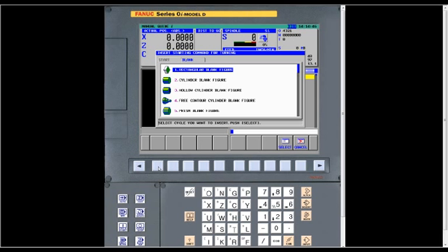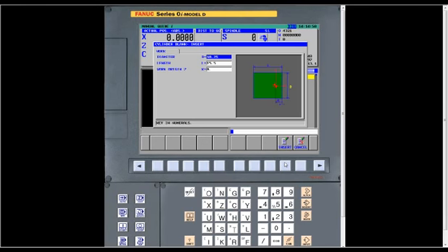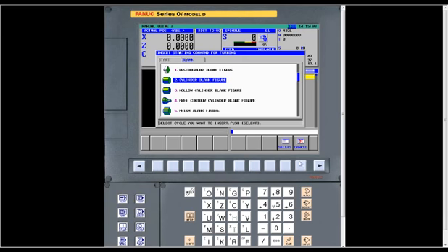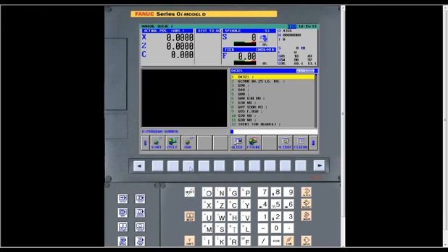When it does the simulation, it'll show a part that's representative of the piece of stock that you're machining. But again, this is very simple stuff, just fill in the blanks. If you select the blank, it asks for a diameter, a length, and a work origin in Z. Very simple. Then cancel out of that.